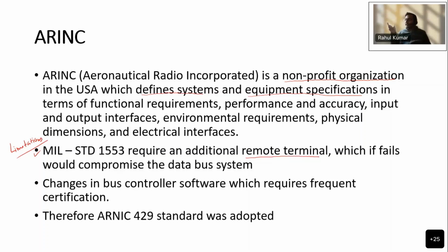Okay, and if that remote terminal fails, then it would compromise that particular subsystem. That subsystem will be completely disconnected from the data bus if the remote terminal fails. Okay, so that was one of the limitations of your 1553 bus system.